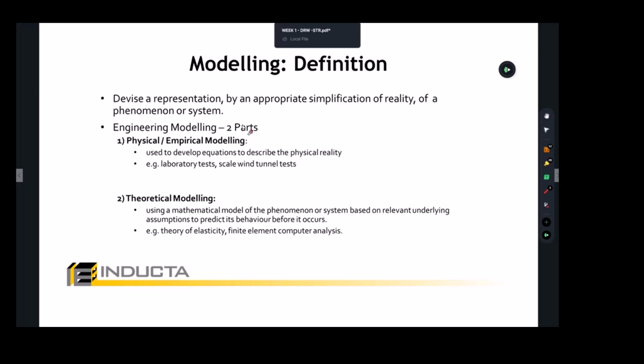So what you really do here, there are different terminologies to talk about modeling, is imagining the intent you want to think about. As I said, we're talking about the subject and what we want to teach you there. You're going to have architectural drawings. If you work with an experienced team of architects, they will know from previous jobs that the core needs to be close to the center and with decent thickness. The wall of the core needs decent thickness because it's resisting lateral loads. That will help you start thinking about it.